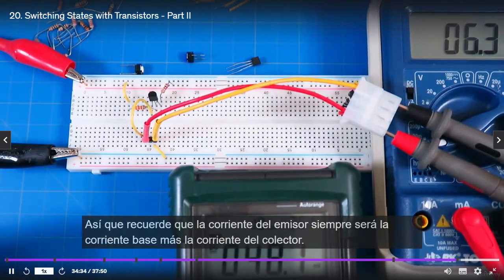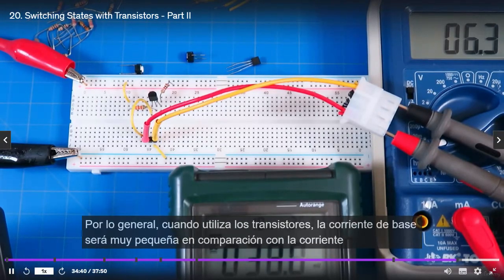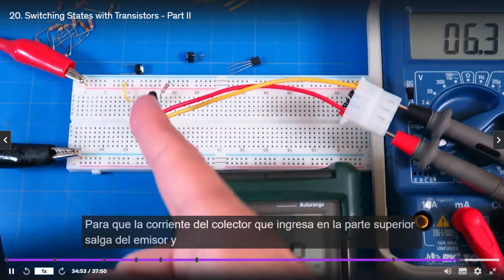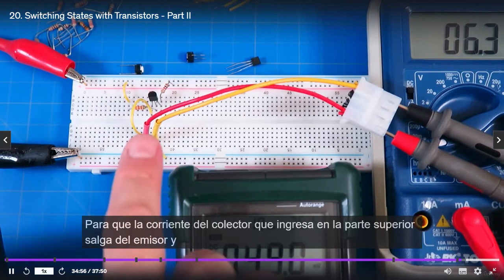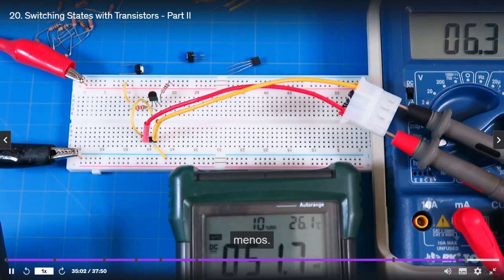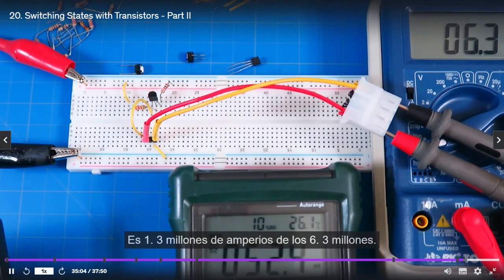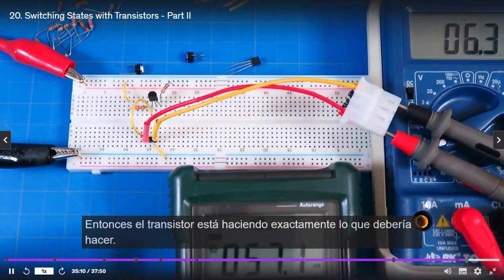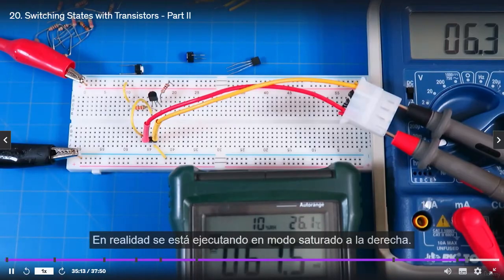So remember, the emitter current will always be the base current plus the collector current. Typically though, when you're using transistors, the base current is so small compared to the collector current that you don't even notice it. The collector current coming in at the top would exit out of the emitter, and if you ignored the base current, it wouldn't make your calculation off by more than 1% or so. But in this case, it's a big chunk. It's 1.3 milliamps of the 6.3 milliamps, so you have to consider it. So the transistor is doing exactly what it should do. It's actually running in saturated mode, all right?